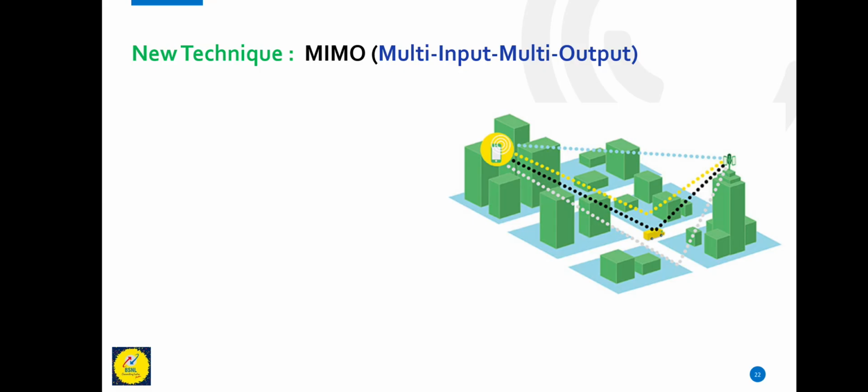In 4G, for example, 2.5 GHz is the frequency used, so that the antenna size, lambda by 2, is less and multiple antennas can be used. So this MIMO technology along with orthogonal subcarrier systems makes high data download possible.